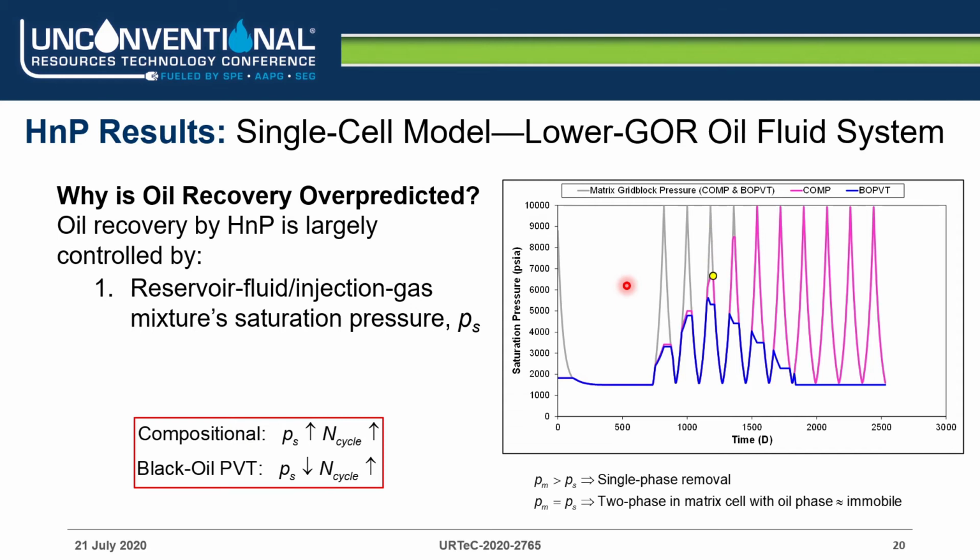The prediction of the saturation pressure is important because it controls when you start to produce 2 phases instead of 1. Now, the nature of a gas-based EOR process is large gas volumes, resulting in most of the cycles here behaving as, when you produce back, i.e. the puff period, the fluid behaves as a gas condensate system, where the gas condensate becomes leaner with each cycle. And we know that producing from a gas condensate reservoir is most efficient in terms of condensate recovery when the gas reservoir is single phase.